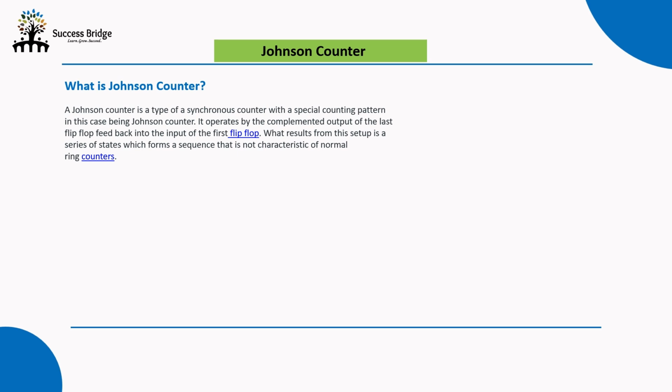These ring counters are used in hardware logic design, for example within ASIC and FPGA ICs, to create complicated finite state machines. A Johnson counter circulates a stream of ones followed by zeros around the ring.